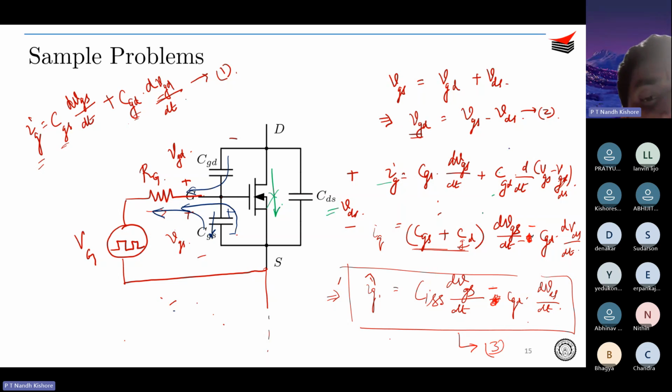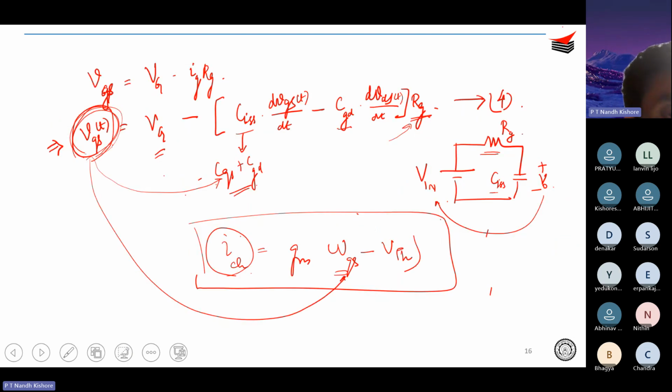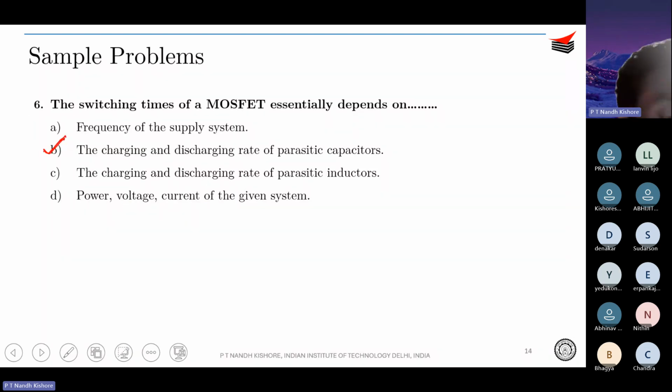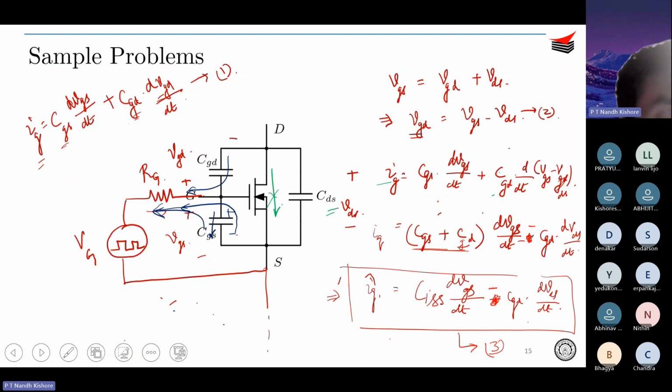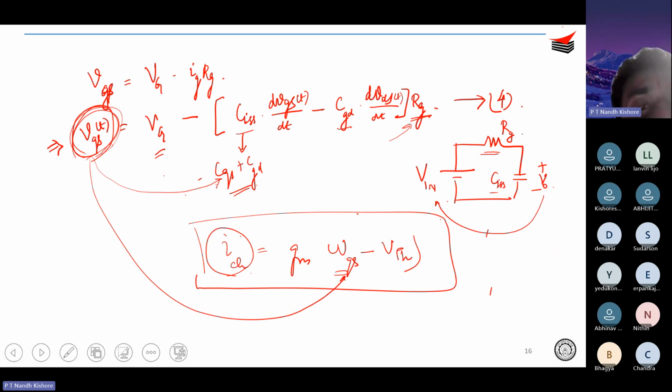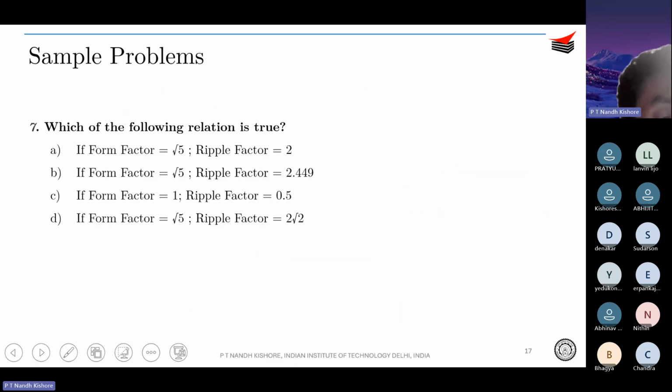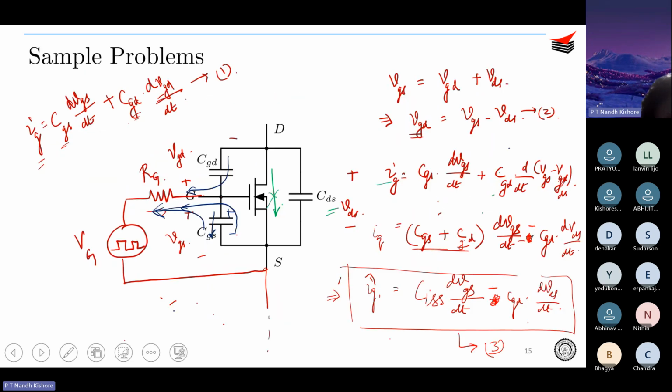So similar equations can be formulated for turn off as well, just that the gate current IG will be reversed. I think it is pretty clear for you guys how the MOSFET turns on, and what the bearing of the capacitance and the RG values is on how the MOSFET charges. So that was about the devices.